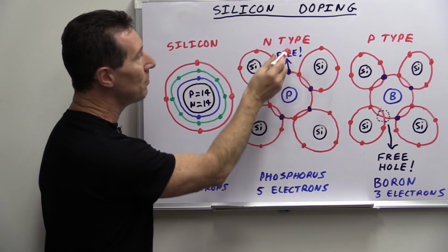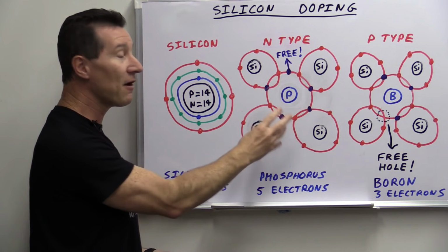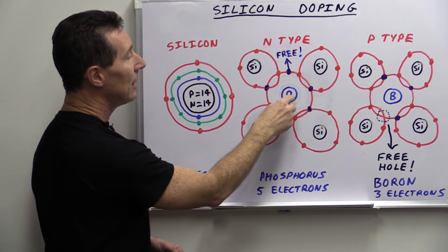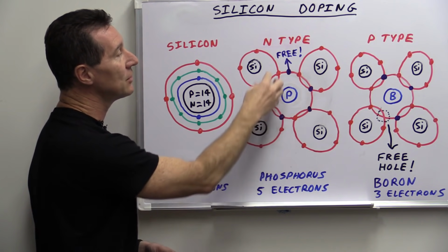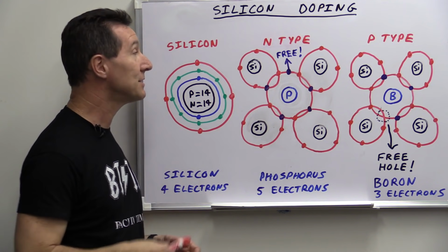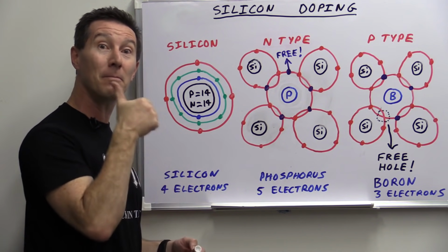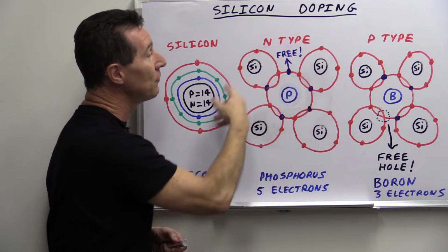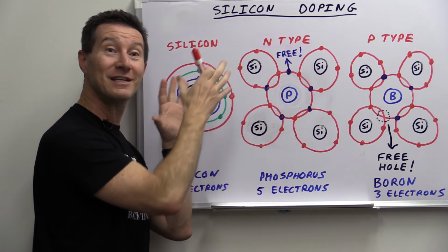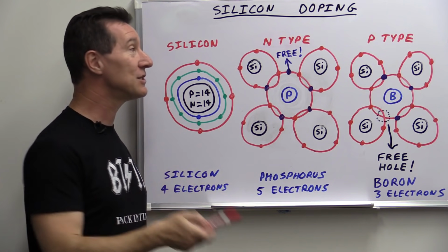But if you dope silicon with a little bit of phosphorus, phosphorus is a very similar atom, but it's got 5 electrons in its outer shell. So if we have a phosphorus atom in here, they actually join up and fit into the silicon matrix very nicely, except because it's got 5 electrons here, there's 1 free electron. Beauty, that electron is free to float wherever it wants throughout the matrix. So bingo, we've got an extra electron that's free to go all the way through and conduct current with. But we also need a matching type called N-type.